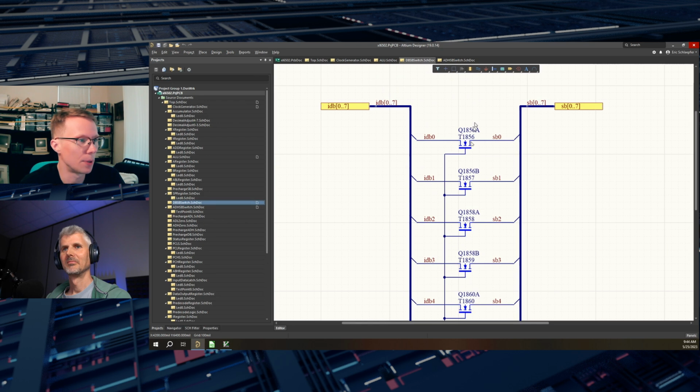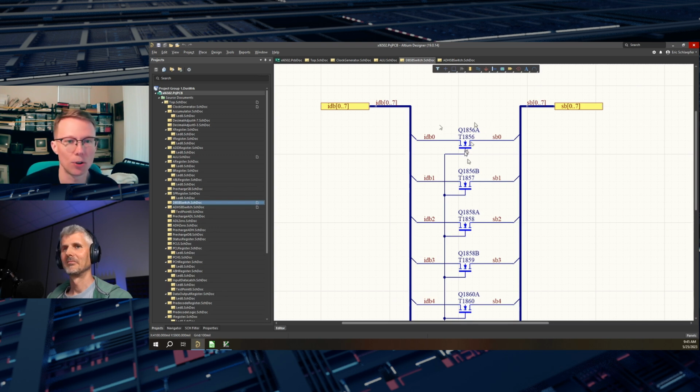The good news is that, of course, the threshold voltage is relative to the substrate, and that's relatively straightforward to get. There's some other effects like channel length modulation and stuff like that you probably remember from semiconductor courses that will have an impact here. And so these are certainly not perfect transmission gates, but they work well enough for that purpose. Where you run into some key differences has to do with the parasitic capacitances as well as the RDS on.